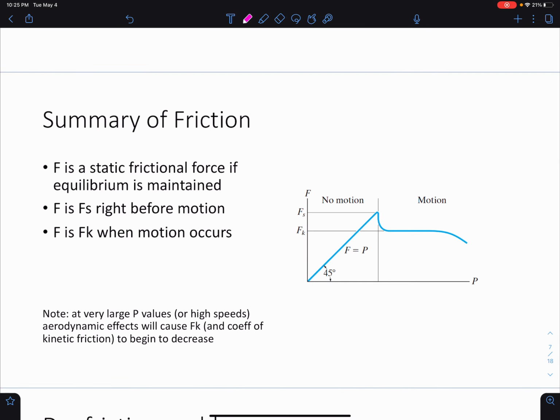So what we're dealing with here is an image that looks like this. The friction force can resist a lot before it gets into motion, actually more than it can resist when it starts moving into motion because it's already given in at that point. So you can resist a lot through Fs, and then once the motion starts, it drops down to Fk. So your Fk is always lower than your Fs. Your system wants to resist this motion. Once it gives in, it's accelerating, it's moving, and you're in that Fk state, which is actually a lesser force required to maintain that motion. Okay.